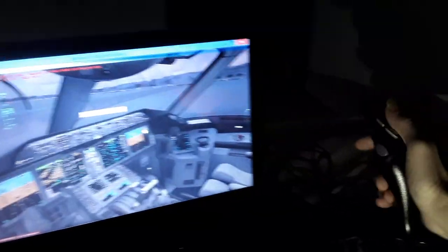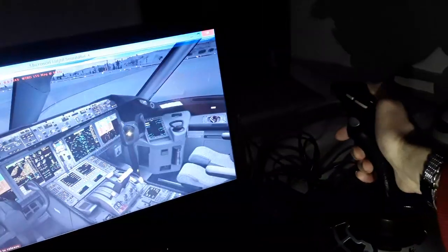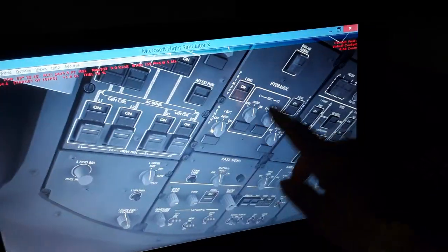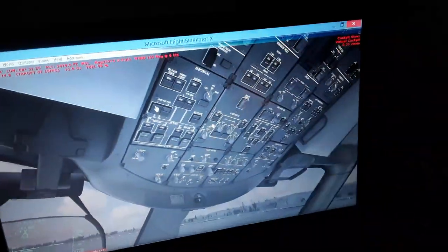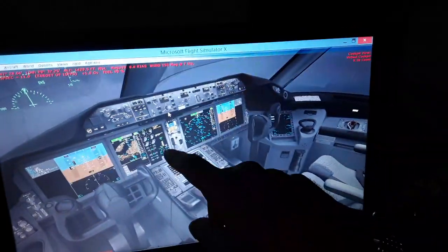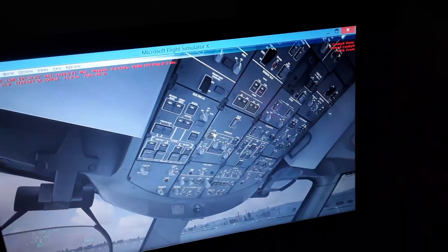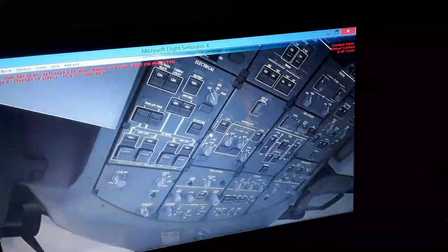Also, the flight control computers control the deflection of the flight control surfaces that I showed you. We also have the hydraulic fluid over here, which is pressurized from the engine and electric pumps, and also from pressurized air. It receives pressurized air from the engines, 5th and 9th stage, to pressurize the hydraulic fluid.